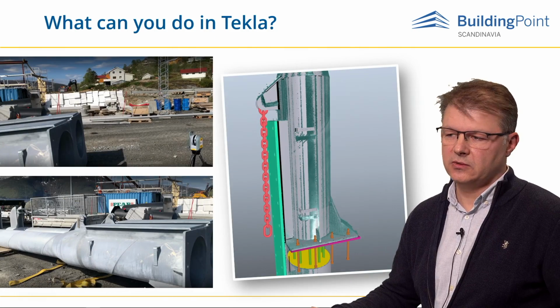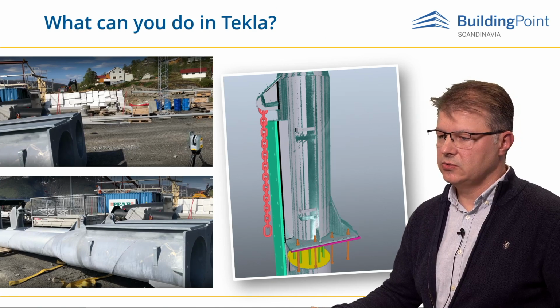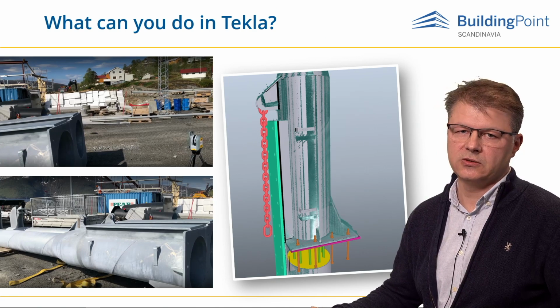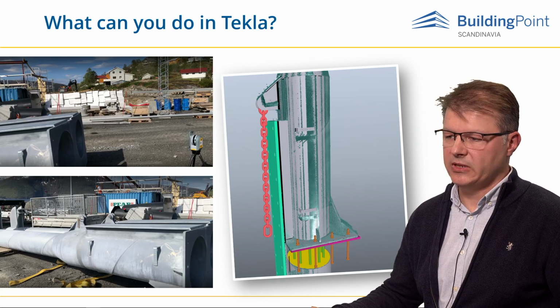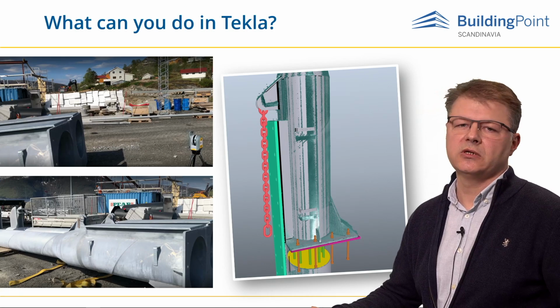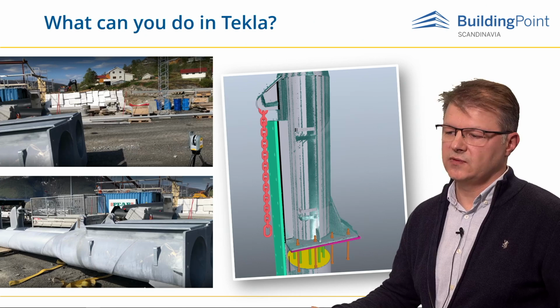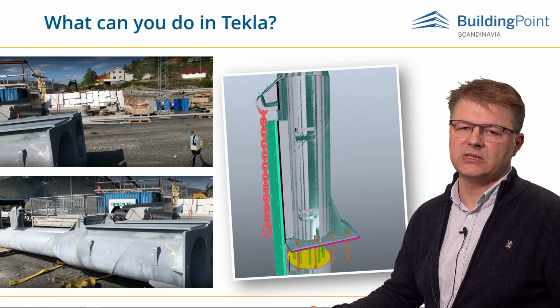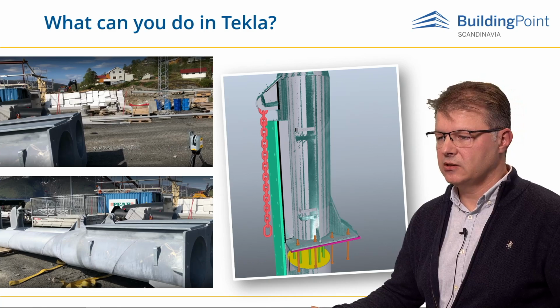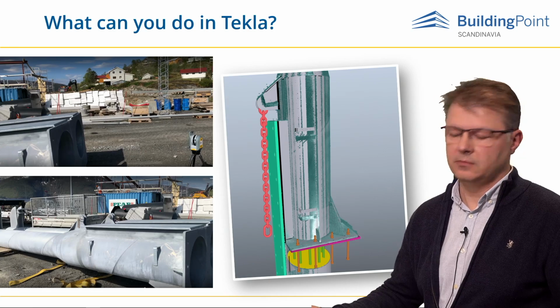Of course, you don't need to just do a point cloud of the whole structure. You can also use scanning on different elements or different assemblies which are going to be transferred to the building site before it's sent. It's much easier to correct mistakes in the workshop than correct them on the building site.